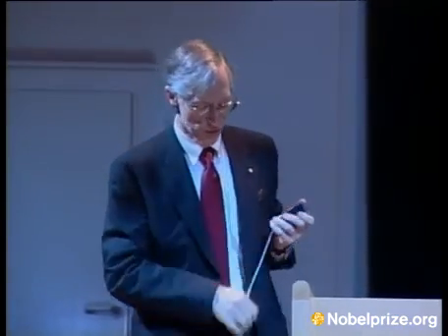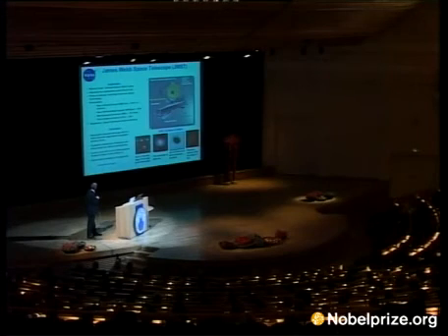The observatory will have this deployable infrared telescope. The mirror here is made out of 18 beryllium segments, and unlike the Hubble Space Telescope, they will all be adjustable so that we can get the mirror shape correct after launch. It's the only way we could possibly build a telescope this big, because it's not possible even in principle to make a rigid, stiff, perfect telescope that will stay in shape, especially if you're going to have to unfold it.